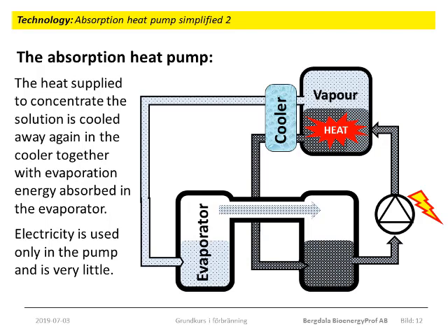Most common in absorption heat pumps for this application is to use lithium bromide in combination with water. Using that, the evaporator can be maintained at some 4 to 5 degrees Celsius, while the need of heat in the distiller is a reasonable district heating temperature, around 90-95 degrees. Let's now look at a practical case.